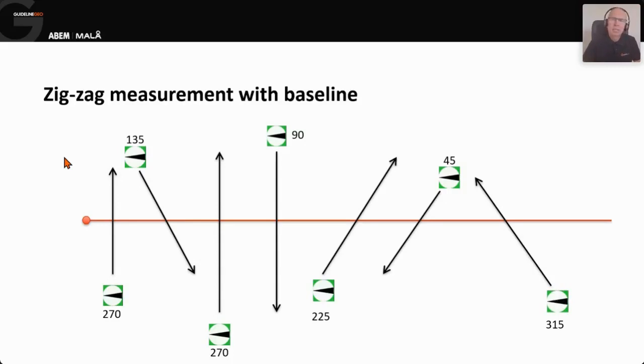You just need to know the distance along the baseline that you've done. Sometimes some people like to do some 45-degree lines across the baseline, and you can do that. So you can just enter that at any point throughout the data collection, just pop that information in. So you don't have to go exactly at right angles.